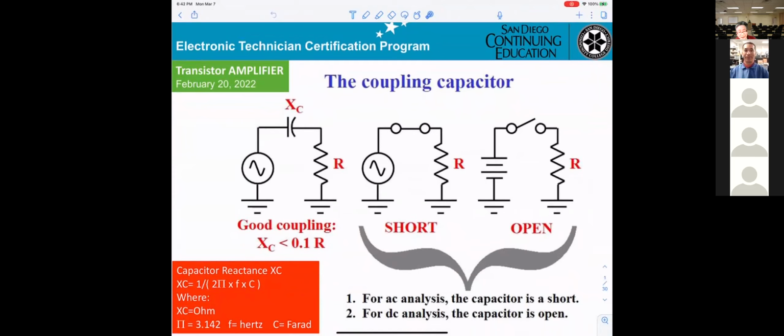amplifier. You get 3 configurations: common emitter, common collector, common base. Also, you understand in JFET, you can get the same thing. 3 configurations for the JFET: common source, common drain, and common gate. If you understand that thing, it's easy to understand another one.